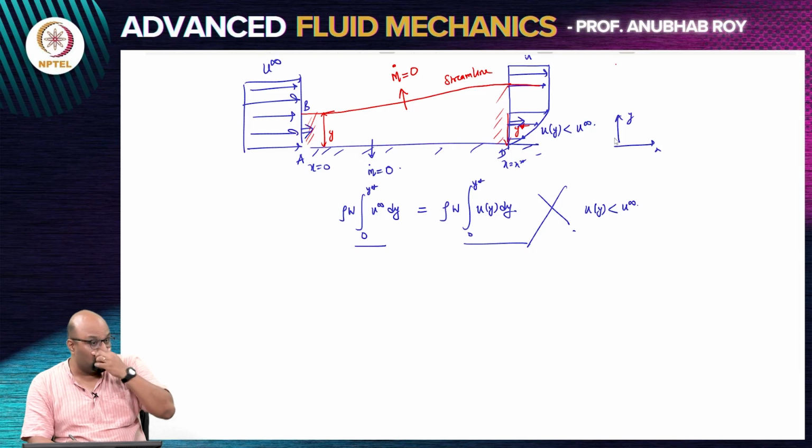You think of it in terms of a pipe. The moment you have a pipe where the inflow velocity is more than the outflow velocity, you know that the outflow cross section is larger than the inflow cross section. That's just the statement of mass conservation. So, you can think of this boundary layer as like an imaginary pipe, because the streamline on top is a no penetration boundary condition.